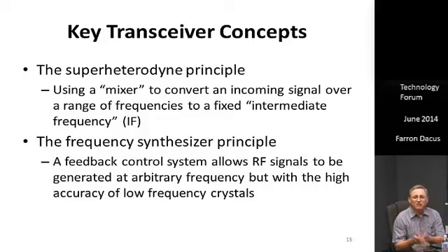So if you've got, say, a voice signal consuming 10 kilohertz of bandwidth, you want to put surgical filtering around that signal and not introduce other noise, because noise is proportional to bandwidth. And it's amazing to me, but true, that most engineers have forgotten this. If they're not RF engineers, they've seen that in one lecture, it's never mentioned again, but that is one of the most dominant things in RF, that noise is proportional to bandwidth, and so you're always fighting to get noise bandwidth as low as possible.